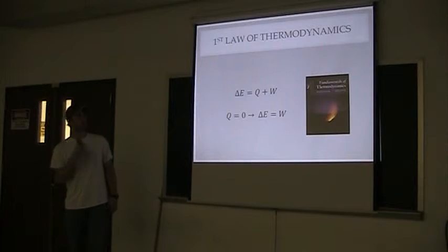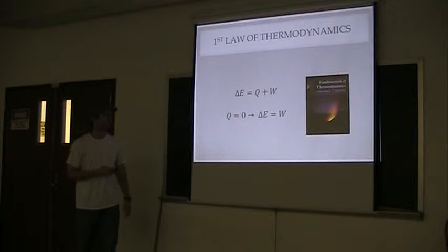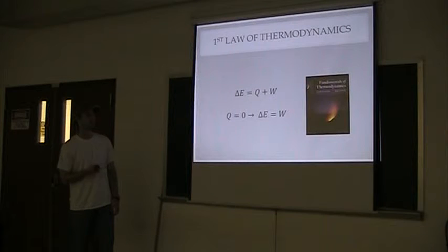Looking at the first law of thermodynamics for this, we have our change in internal energy. If we look at a specific control volume of water, the only change in internal energy comes from the potential energy, which is the change in height. That potential energy does work, and that work out is what's being done by the turbine. That's where the work takes place. Then it flows into a lower reservoir, and we can pump that water back, like I said earlier, into the upper reservoir to regain that potential energy.